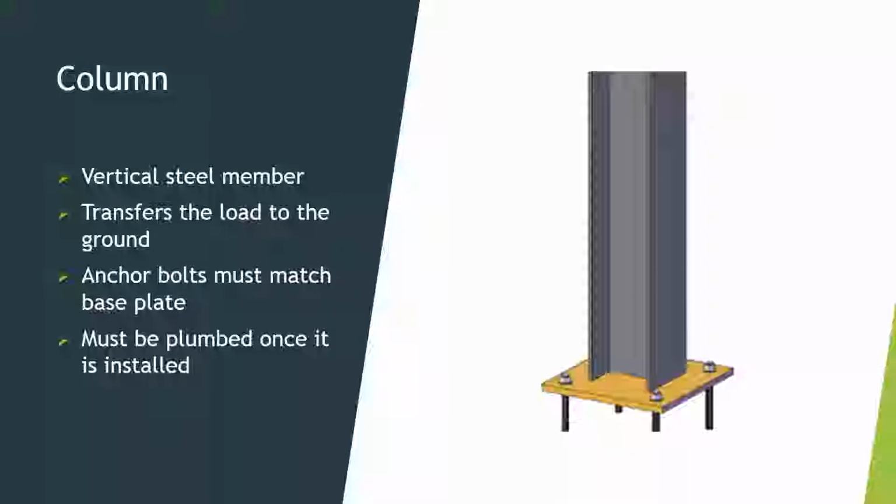So the first structural steel member which is erected in a steel building is the column. This has to be rigged properly so that the column hangs vertical and plumb. A shackle and a wire sling or bull tail, which would be one shorter choker, choked to the column, and a longer choker hooked above the ball of the crane. The base plate at the bottom has to correspond to the anchor bolt pattern that's preset in the concrete pier. Then the column is to be positioned so the holes in the base plate match the anchor bolts.